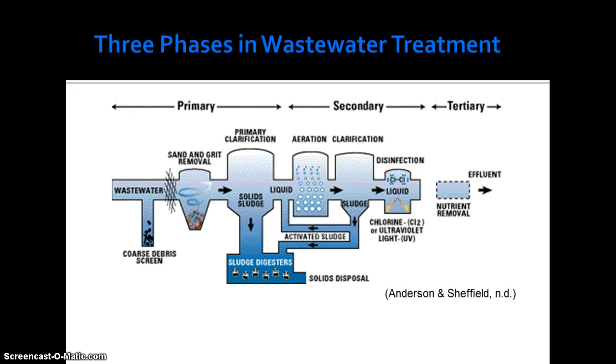The final step is called tertiary or advanced treatment. This step filters most dissolved inorganics and remaining dissolved organic compounds, providing for low nutrient waters for downstream discharges, deep well injections, or other means of disposal.